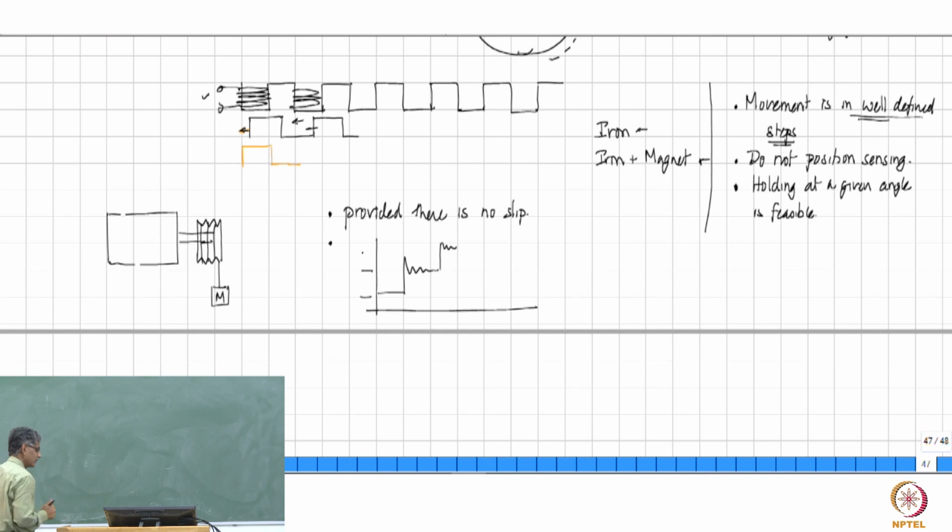So that is then known as micro stepping. So you can do that and attempt to hold the rotor anywhere else, and if you are doing that, then these oscillations are not likely to occur because you are moving in a gradual manner. But one has to be slow enough. You cannot do it very fast because again it might slip.